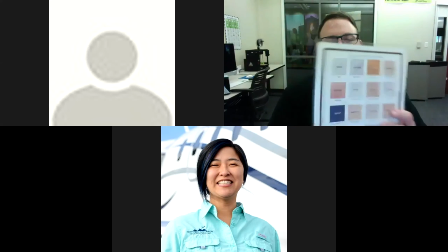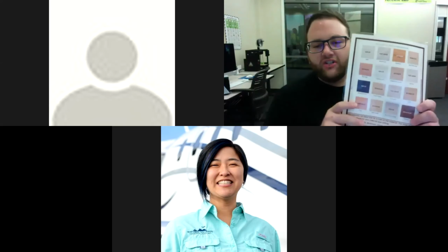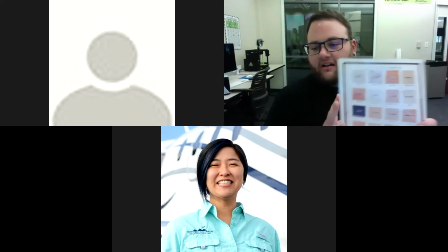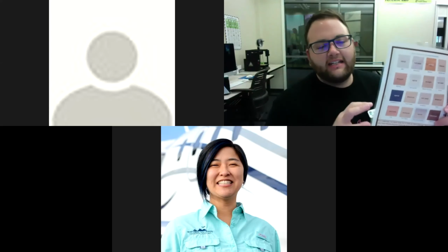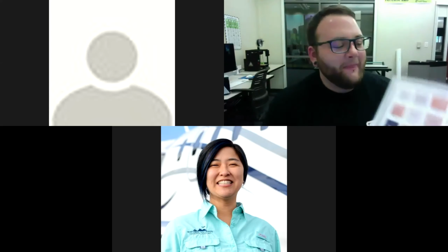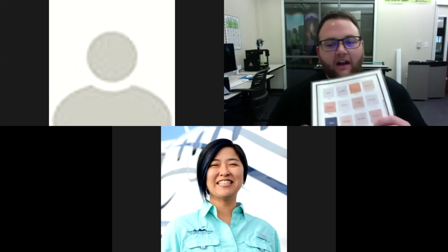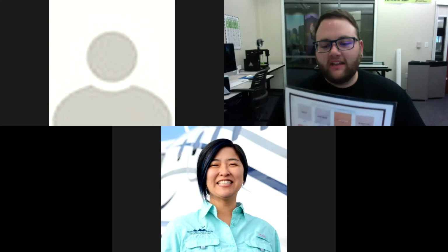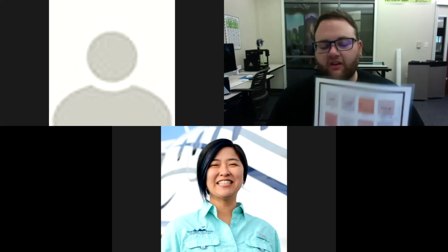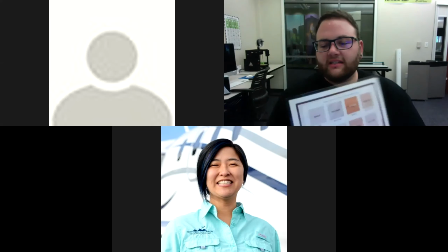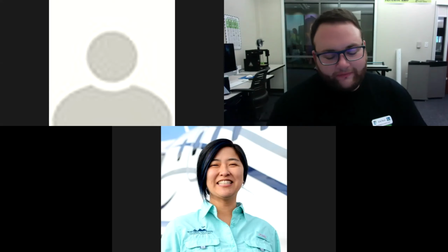I don't know why this is just our safety handout here. I think I didn't add it to the handout, sorry. But we actually have a list here of what bits go best with what materials. This can be found on Easel, but for MDF, the down cut bits are the best. And so I'm going to try to get this sent off to you guys. If not though, it's literally right next to the machine so we can kind of take a peek. So for MDF, down cut bits are the best.